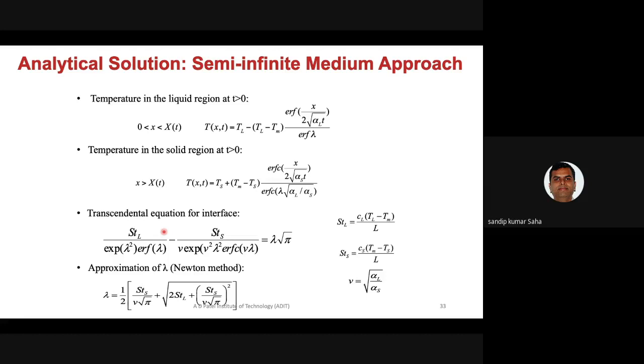Okay, in this case. Now, if I devise a numerical method or computational fluid dynamics model which needs to track the melt front explicitly, that means I need to move the mesh with the speed with which this melting is occurring. Okay, and it is not very easy. Moving the mesh with the speed with which the melting is occurring is not very easy to calculate every time, and it will increase the computational cost.